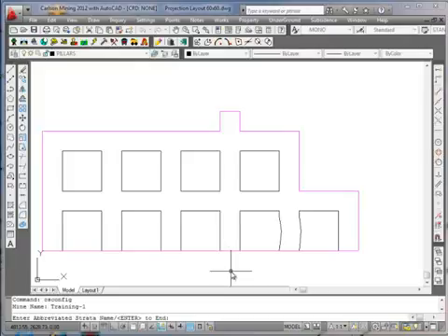And we'll enter the abbreviated strata name, and since we're starting at the very top of what we would expect to see in a mine, the first layer I'll put in will be R, and indicate that that's going to be roof, in case any out-of-seam dilution was taken in the roof. And we would expect to see in this case maybe coal next, so I'll put a C in there and describe it as coal. And if there's an internal parting, I'll identify it as such.